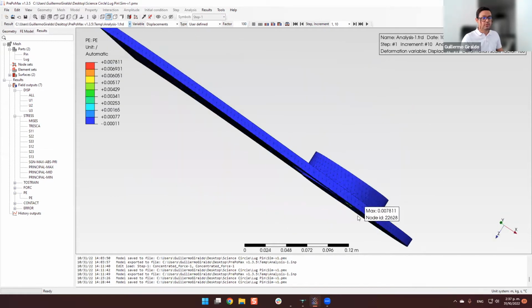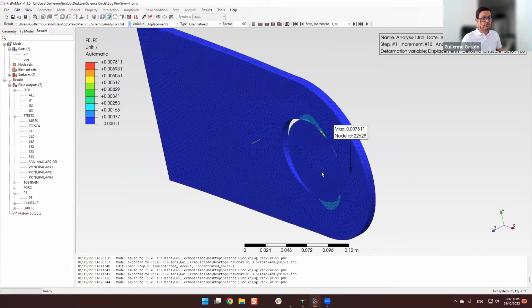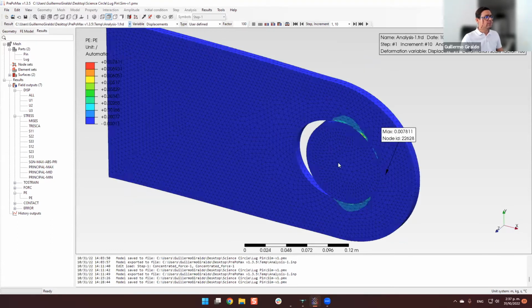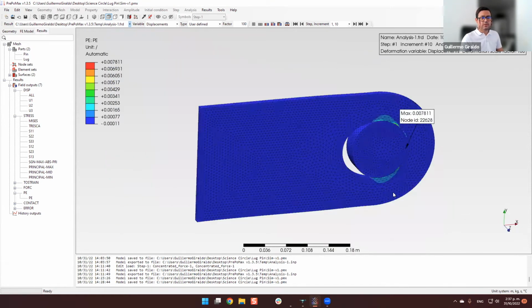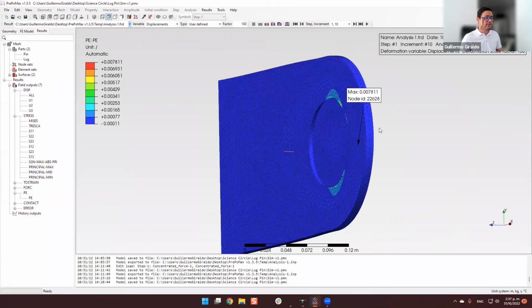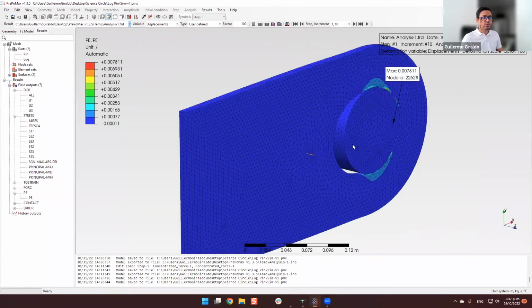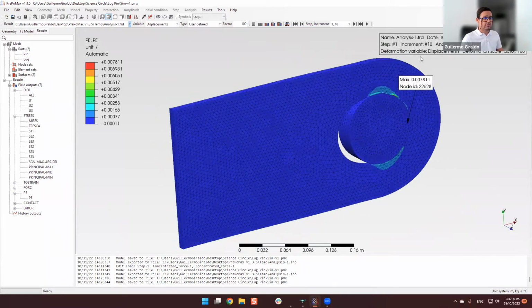You can see there is also a little bit of a side deformation here that is visible when exaggerated. But what I want to do here is two things. The first one: you can see the lateral deformation, and I want it to be a purely uniaxial case. For that, we will implement a little bit of what we talked about in the last session, which is to leverage the symmetries in the system.